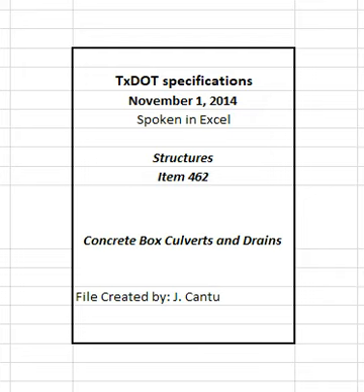3.2 Placement of boxes. Place the box sections in conformance with the plans or as directed when precast boxes are used to form multiple barrel structures. Place material to be used between barrels as shown on the plans or as directed. Start the laying of boxes on the bedding at the outlet end and proceed toward the inlet end with the abutting sections properly matched unless otherwise authorized. Fit, match, and lay the boxes to form a smooth, uniform conduit true to the established lines and grades.